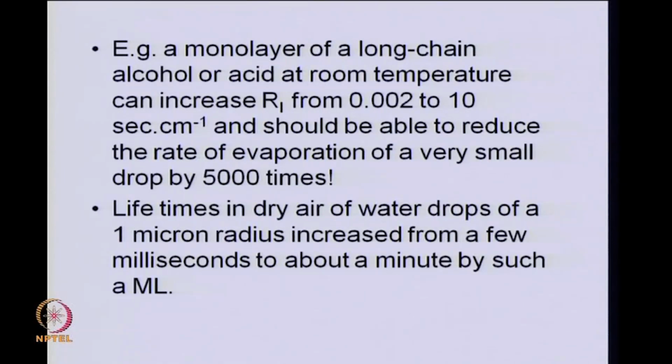Lifetimes of fine water droplets in dry air, when the drop size is about, let us say, a micron radius, could be increased from a few milliseconds to almost a minute, just by the effect of the interfacial resistance imparted by presence of a monolayer.